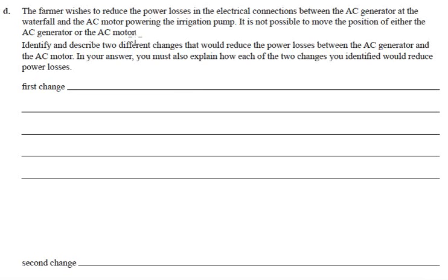Alright. Power loss, this is really saying what is the power loss in the power lines. And hopefully in your notes somewhere you can find that the power loss in power lines, P loss, is equal to I squared times R. The current going through the lines times the resistance of the lines. So if we want to make this smaller, we could either make I smaller or make R smaller. Those are our two different changes.